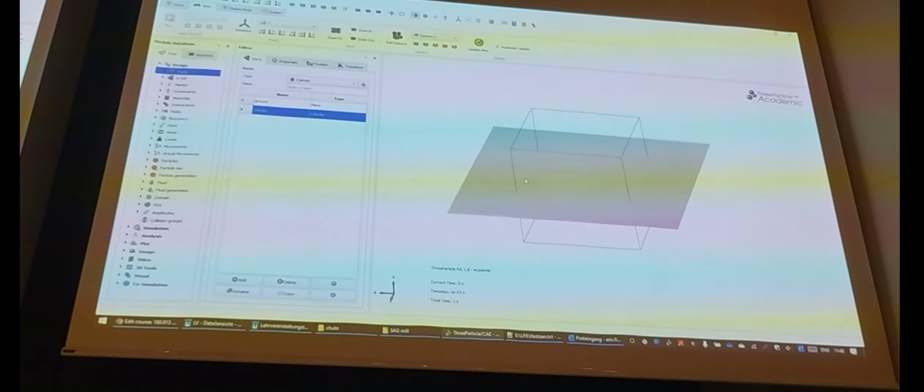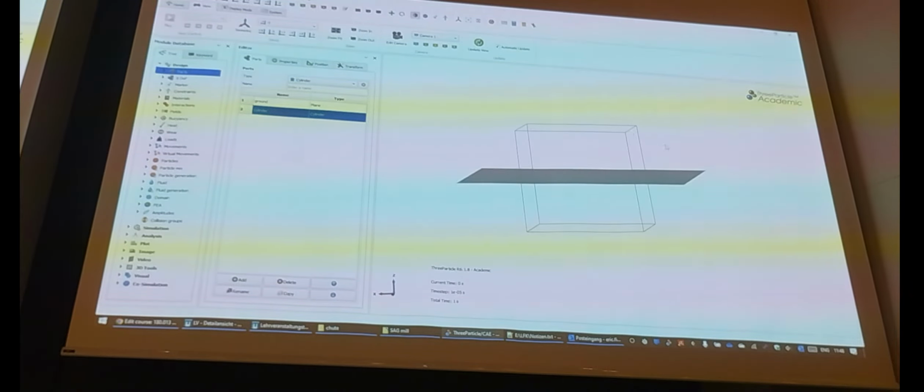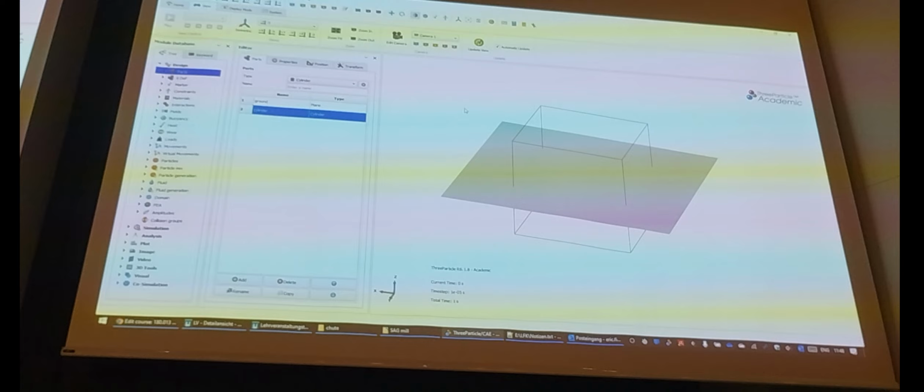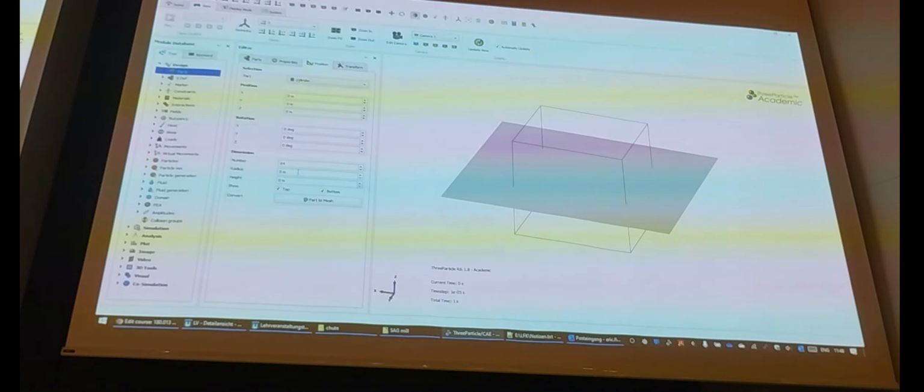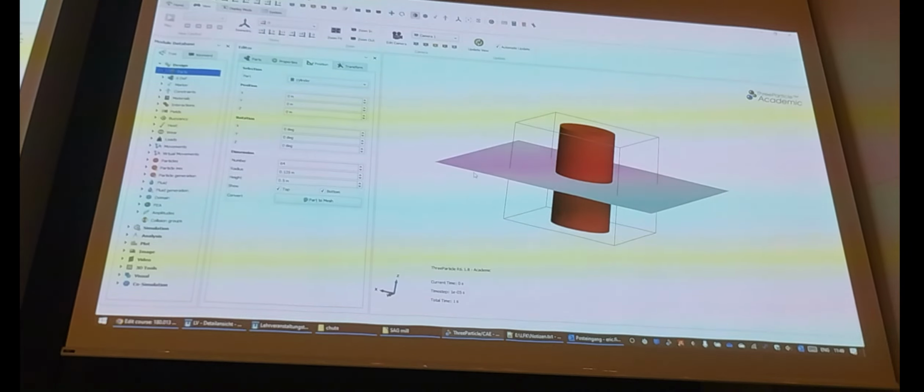So we have the ground with 1 meter times 1 meter, that is default, but you can't see the cylinder because when you go to position, the cylinder has no radius and no height yet. So if I increase that a little, I can already see it. It's too big. Let's say 25 centimeters would be good, I guess. I think it's the size of the thing we have in the lab. 25 centimeters in diameter, and half a meter in height is also cool. 125, yeah, that's the radius, so it's 250 diameter.